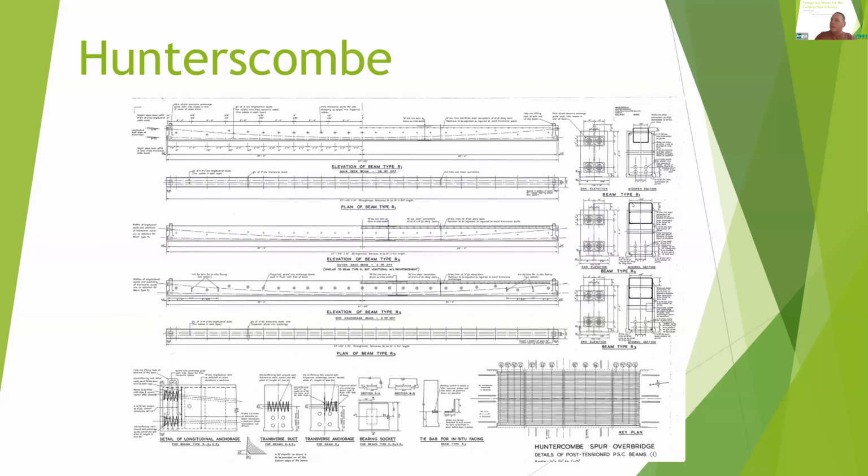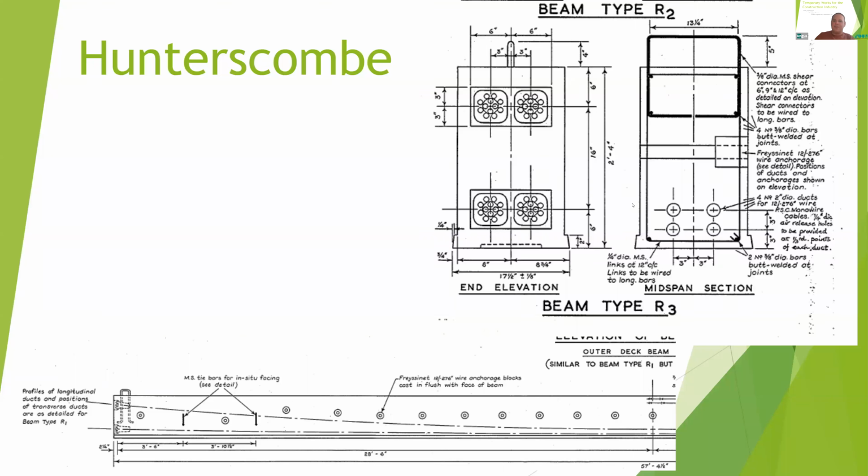In fact, there you go. I've done an enlargement already. Should have thought ahead, shouldn't I? So that's the anchorage at the end of each beam, and then a close-up of a tendon running through the structure. You can also see the lifting eyes here. So that again indicates that these were precast and then pre-tensioned and then lifted up onto the piers, and then the rest of the deck's installed from there.